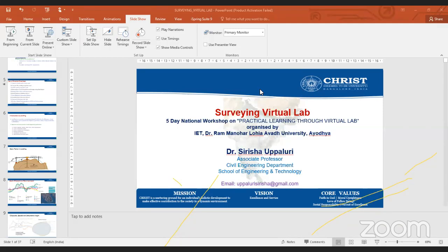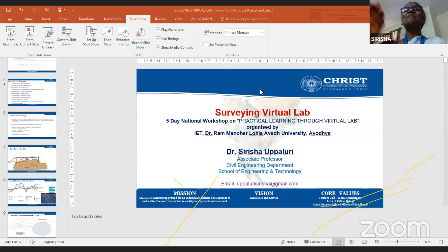Ma'am, there is one more question from Shreyas Saxena. He is asking, how do we change the ellipsoidal height to MSL height? Yeah, ellipsoidal height to MSL height means it is a transformation technique. The ellipsoid is a global datum. MSL is a local datum. So we have a 7-parameter model we are going to perform, which comes under physical geodesy. The x-axis translation, x-axis rotation, y-axis translation, y-axis rotation, then z-axis rotation, z-axis translation, and one scale change.